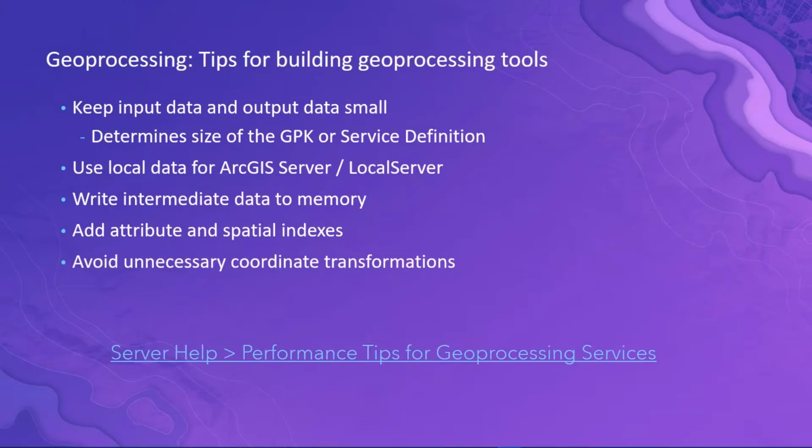Also try and avoid unnecessary coordinate transformation. If you are in control of the data that you're using, then you want to make sure that you have all your data in the same projection, so that it doesn't need to do coordinate transformations as part of that analysis. That definitely saves a little bit of time when the tool is running. Having said that, if you need to keep the data in its native projection, you can do that, and you can add in that coordinate transformation as part of the process, which can also be very powerful.